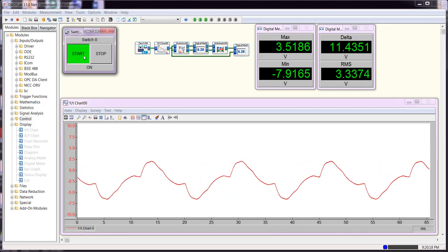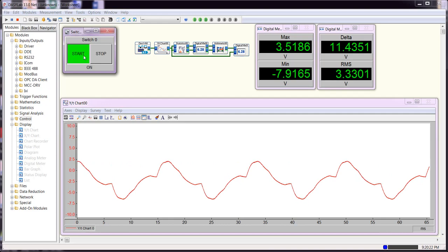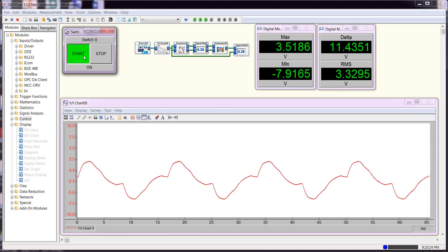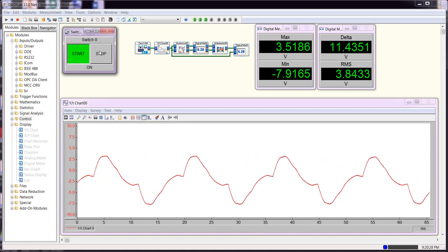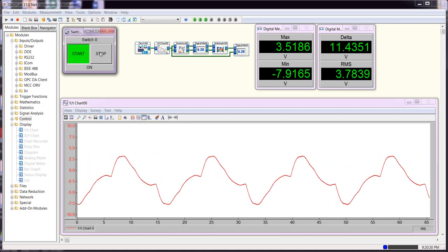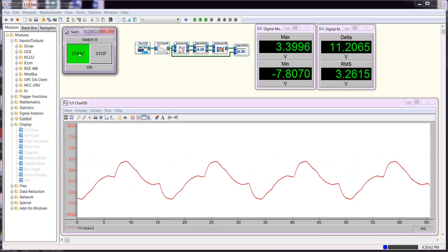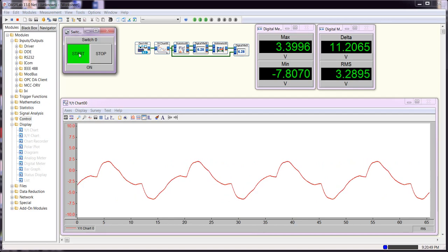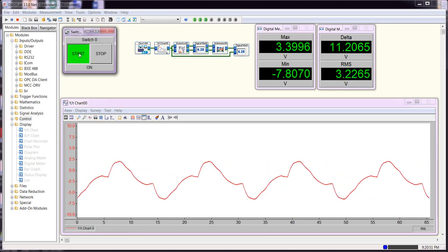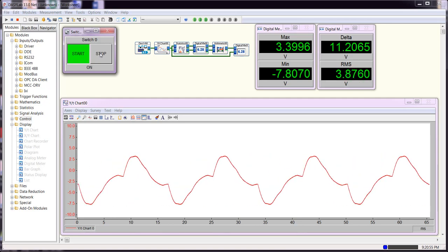And our RMS is 3.2 as compared to our 2.21 on the Fluke. That's interesting. That's kind of a big change there. If anybody knows why, make a comment. I'll dig into it some more myself, possibly. The wave is interesting looking. I expected more of a square wave than a modified sine wave. We'll see what the other ones look like.